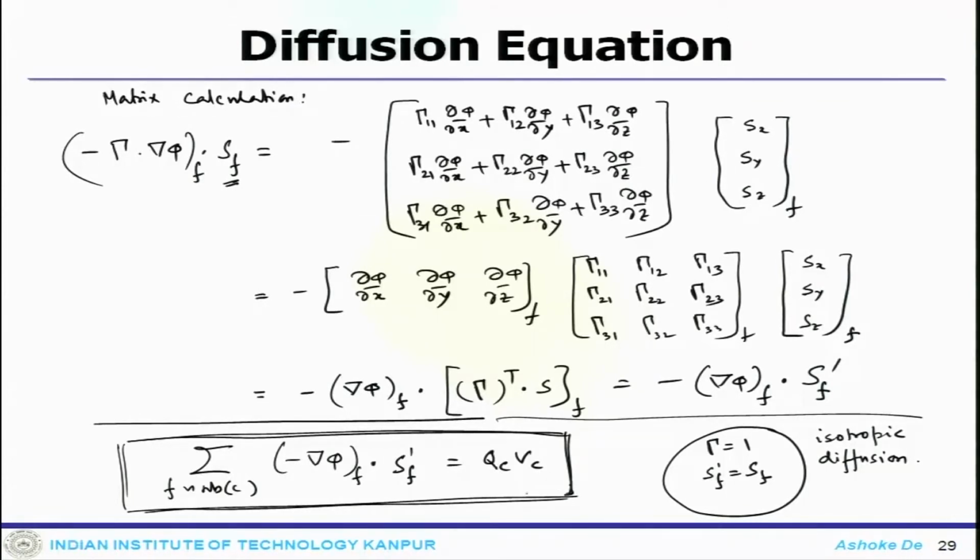If you replace the tensor with a single coefficient, that brings the whole system down to an isotropic diffusion system, which is a special case of the anisotropic system. Similarly, when we derived the discretized equation for a non-orthogonal unstructured system, the special case is the orthogonal system, where the cross diffusion goes away.